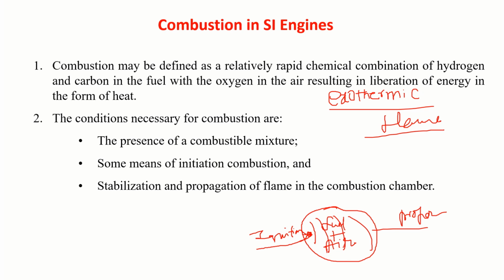Once you have initiated combustion, there should be stabilization and propagation of the flame. You should create conditions in such a way that the flame propagates with a particular speed, and as it travels it consumes the charge and continuously releases the energy. So these are necessary for combustion of the fuel.